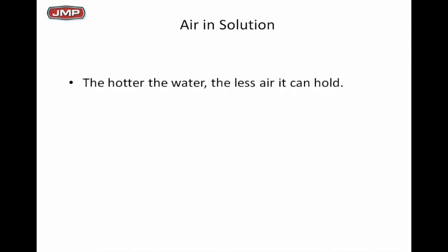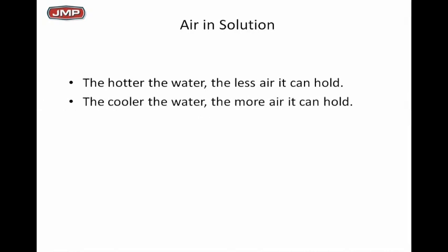So how about air in solution? What do we know about air? The hotter the water, the less air it can hold. You know what a deaerator does for a living? Basically, you heat the water up to drive air off. So if you cool water down, you suck air in. So the hotter the water, the less air it can hold. The cooler the water, the more air it can hold.